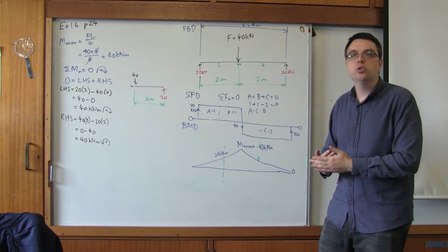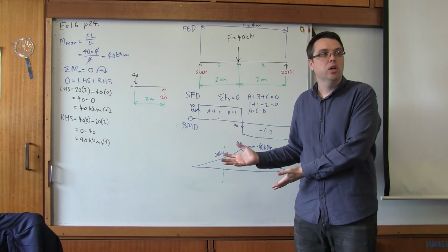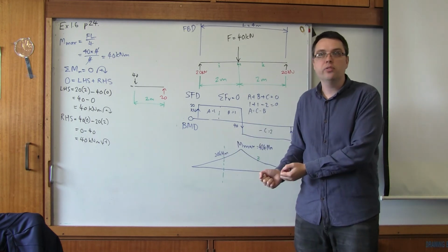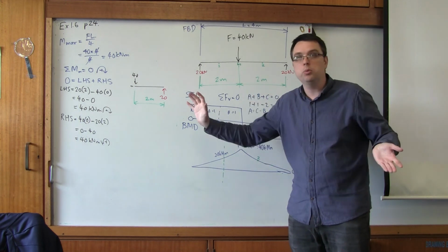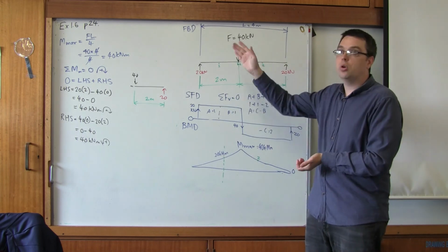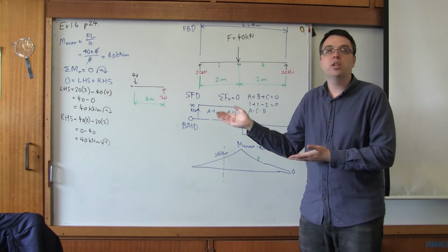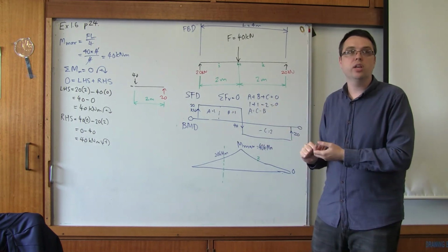Why do we need to be able to produce these diagrams? So we know how much reinforcing goes in the concrete, to make sure that the steel is strong enough. If the client tells us we have to use this size steel, we say in that case you need to put the load somewhere else, because you need another support. You need to change the load condition, because otherwise this is going to be unsafe.